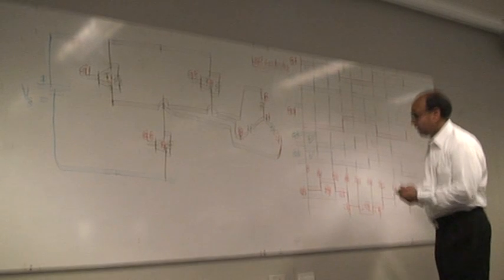So even in the crude method, you can see as if you are getting a nice sinusoidal, like that. But this is of course the crude way. Actually you do PWM. In PWM, your voltage will have a much higher fundamental component with very low harmonic component.